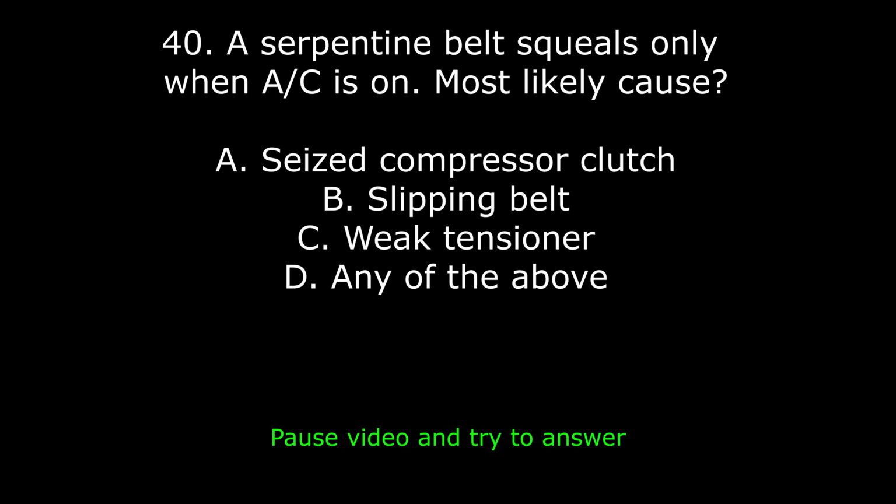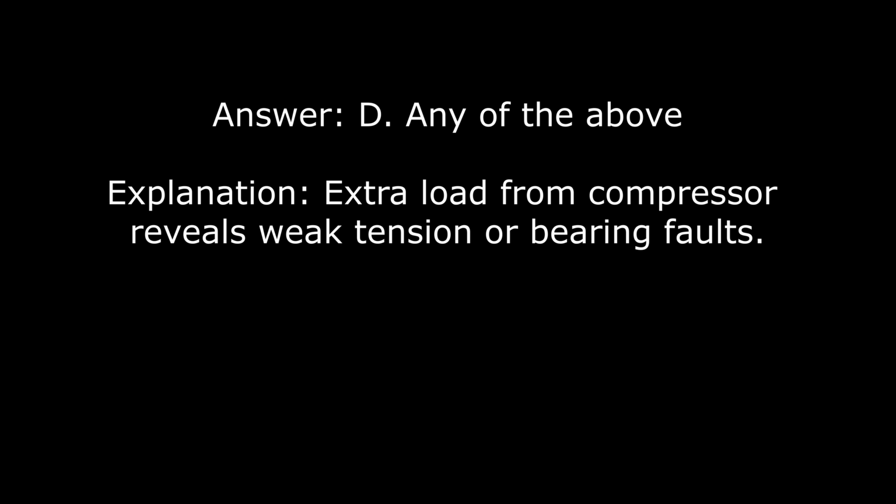Number 40. A serpentine belt squeals only when AC is on. Most likely cause: A. Seized compressor clutch. B. Slipping belt. C. Weak tensioner. D. Any of the above. Answer: D. Any of the above. Explanation: extra load from compressor reveals weak tension or bearing faults.